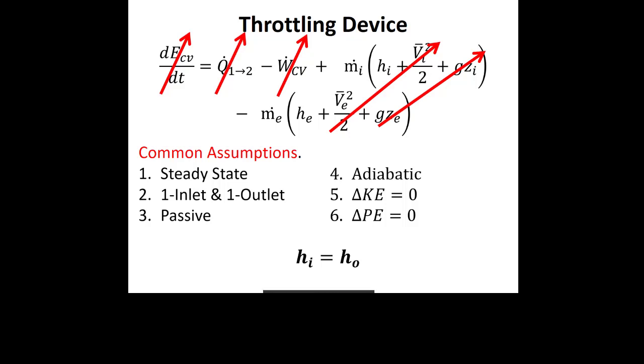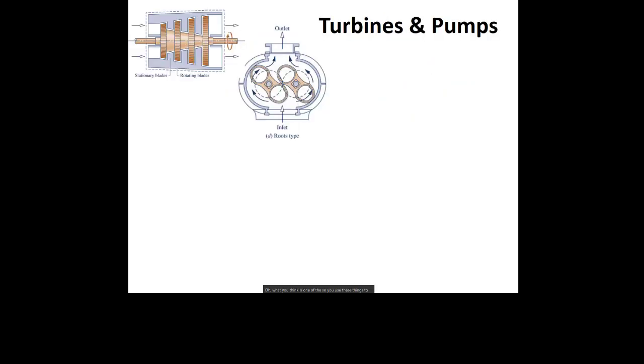So let's say before you're going into one of those direct mixing heat exchangers, you want to make sure that you don't get backflow, that you have one high pressure flow and one low pressure flow, and then you get flow going out what you think is one of the inlets. So you use these things to try to equalize the pressures inside devices.